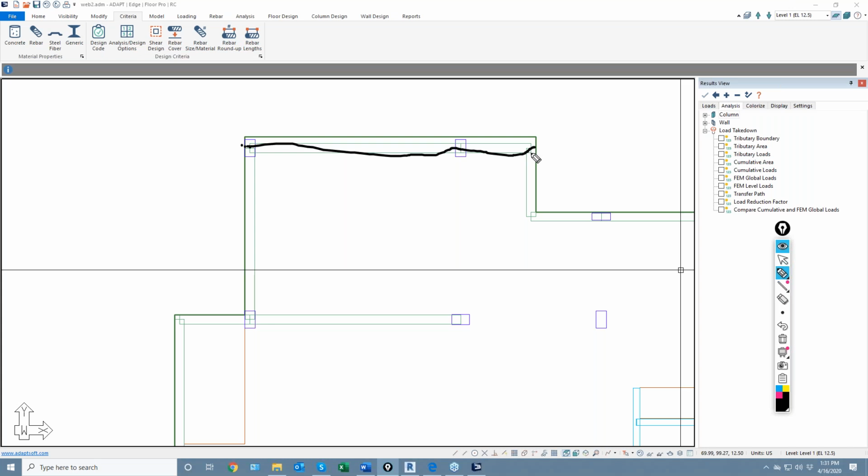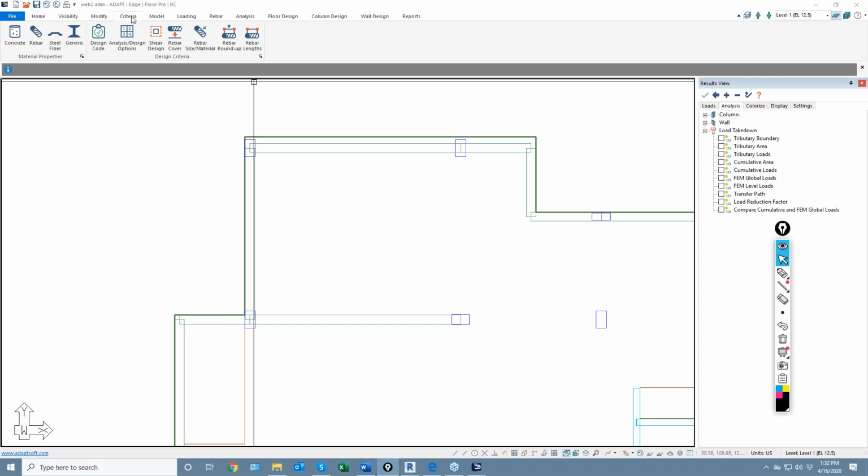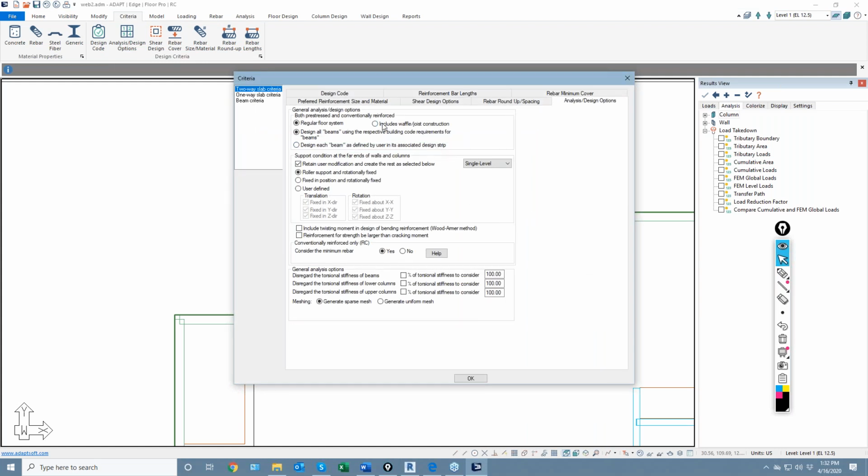Technically, you only have to do 1 per beam segment. So that can be, if you're a new user to this, you don't know that can obviously cause issues. So if you have beams in any of your models that are structural, I always recommend to use this option, include waffle/joist construction. That just means if a design cut cuts through a beam, regardless of how your support lines are laid out, it will always include the beam stem as part of the physical section that will structurally resist the bending and so on.